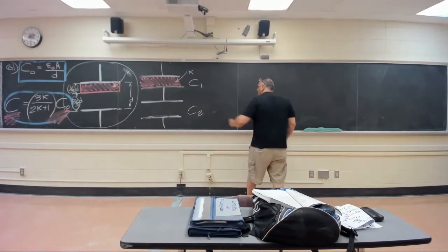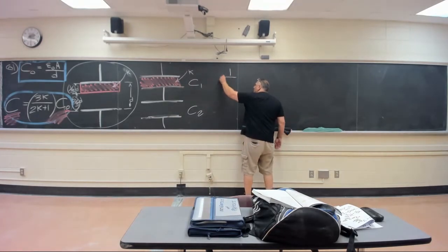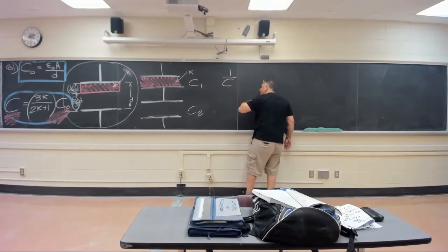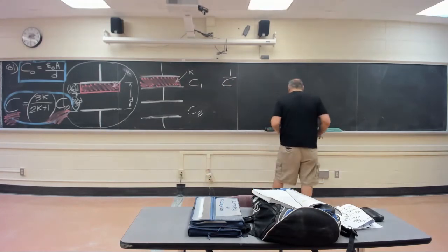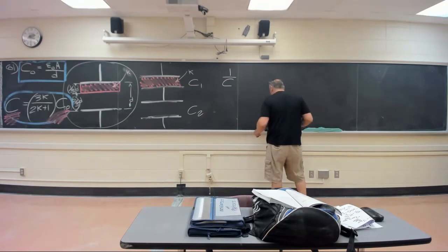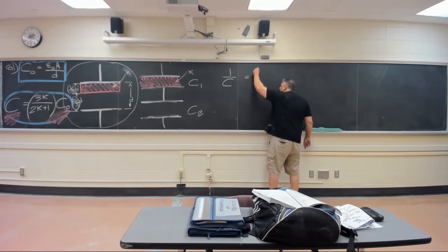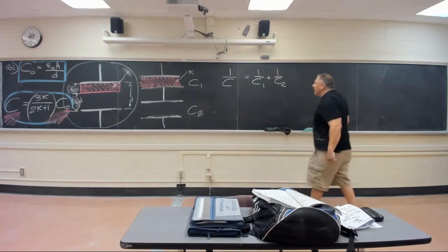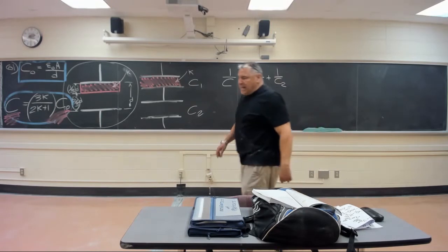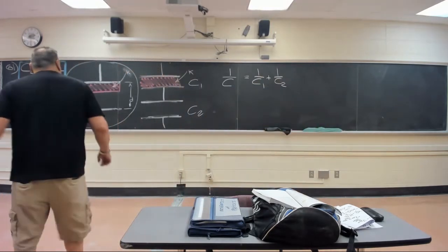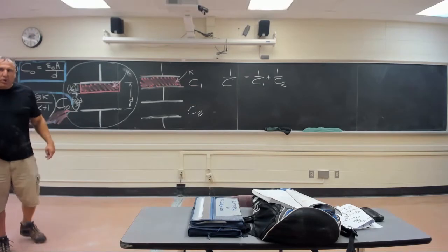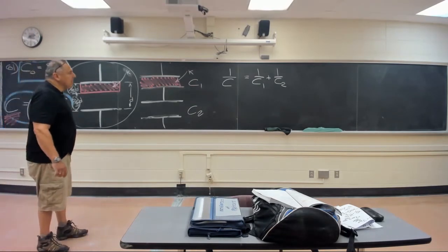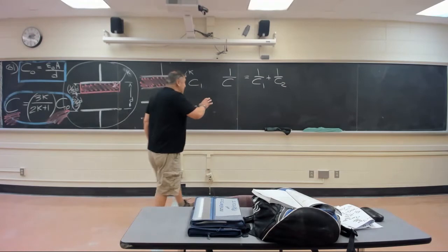So we'll see what we can say. We know if they're in series, the voltages add up, but the charges don't. The charges are identical, only the voltages are adding up. And that's why this works, because the voltages add up to the total voltage, but the charge is the same.